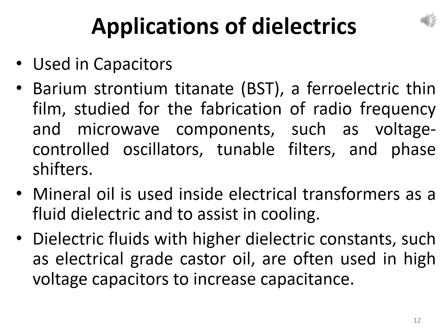In the case of liquids, mineral oil is used inside electrical transformers as a fluid dielectric, and it is used to assist in cooling. Dielectric fluids with higher dielectric constants, such as electrical grade castor oil, are often used in high voltage capacitors to increase the capacitance. So there are different examples of gas, solid, and liquid dielectrics that could be used in capacitors, transformers, and for other engineering purposes.